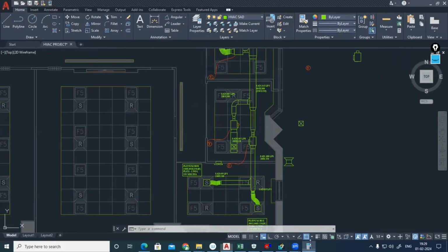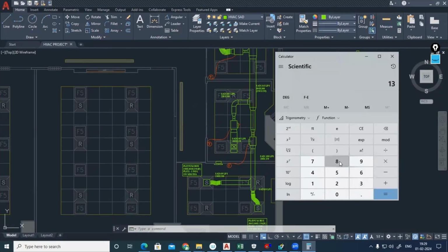Correct. From here, 138 liter per second. Then from here, it is 138 plus 105, that is 243. So 243 liter per second, how much we need? 243, I'm converting into divided by 1000. So 0.243 meter cube per second with 2.5 meter per second of velocity, divided by 2.5. So this is the area of wall opening. If you are taking the square root of this one, 311 into 311. 300 by 300, keep it there, no problem. 300 by 300 wall opening I need there.